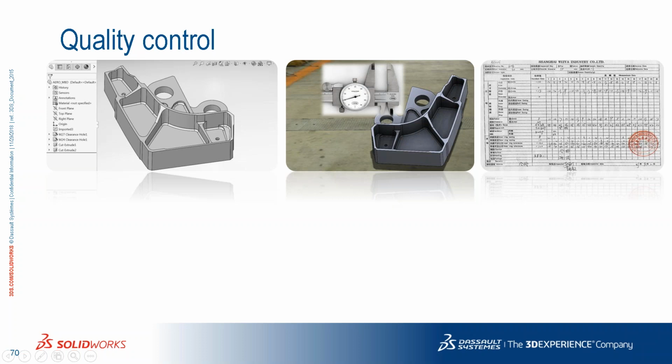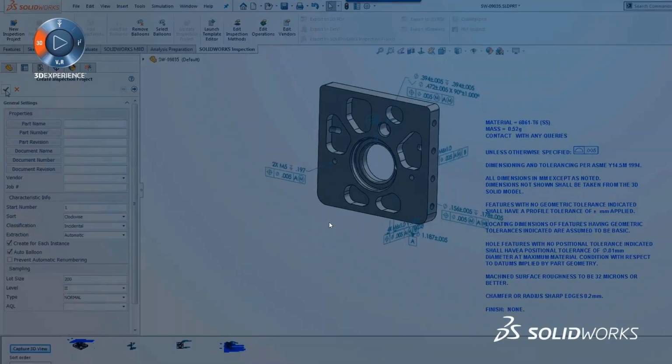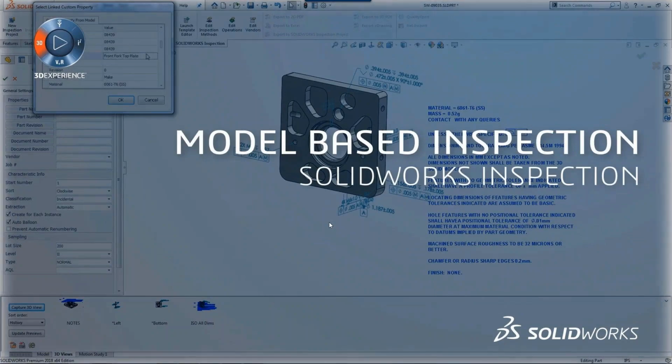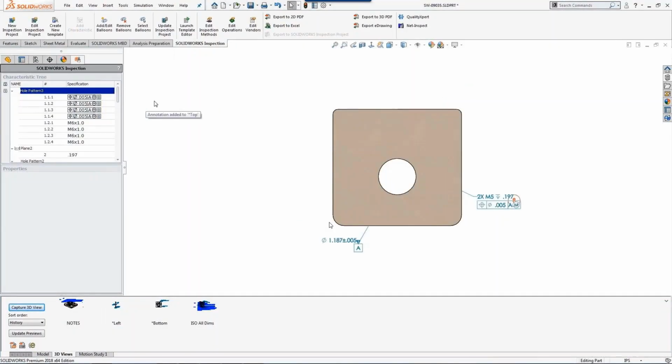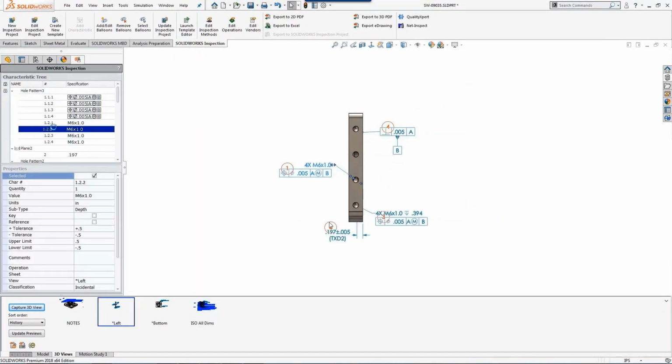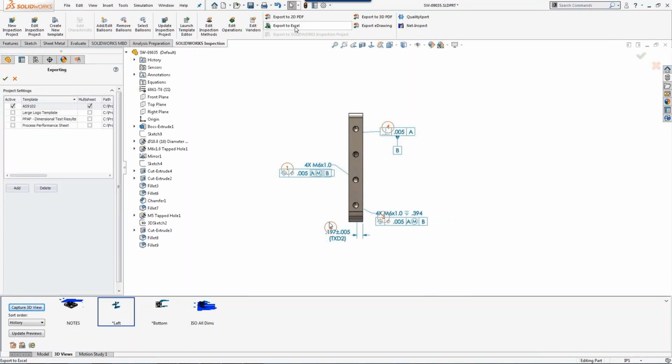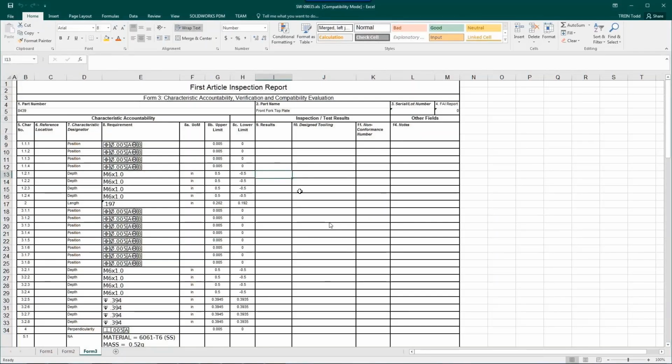We've improved and helped the work of quality inspectors by releasing SOLIDWORKS Inspection for 2D drawings. But I wanted to show you in the application for Urban 626, we're even more accelerating the process because we're doing inspection reports from the 3D model. So you can run the inspection report creation, and SOLIDWORKS Inspection will balloon the MBD dimensions directly. And in a few seconds, you are ready to go out with the report. So imagine how quick it is to create a quality control plan for Urban 626.